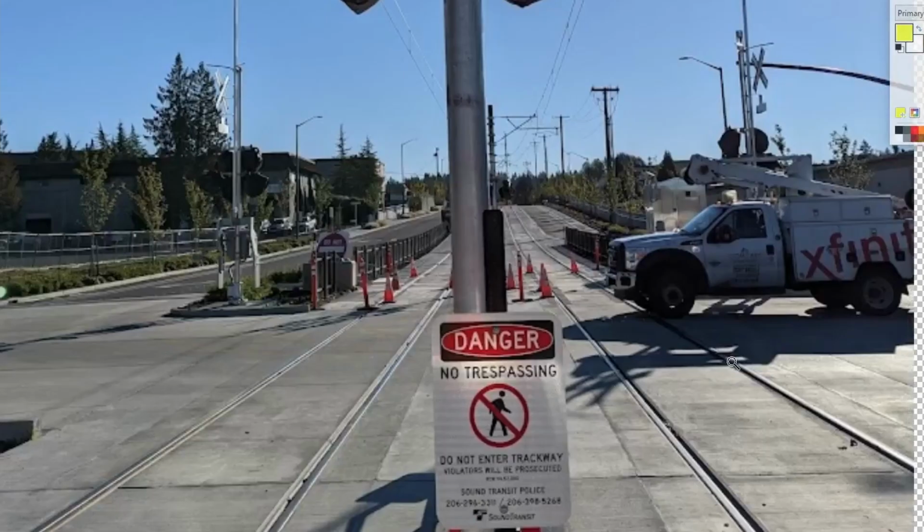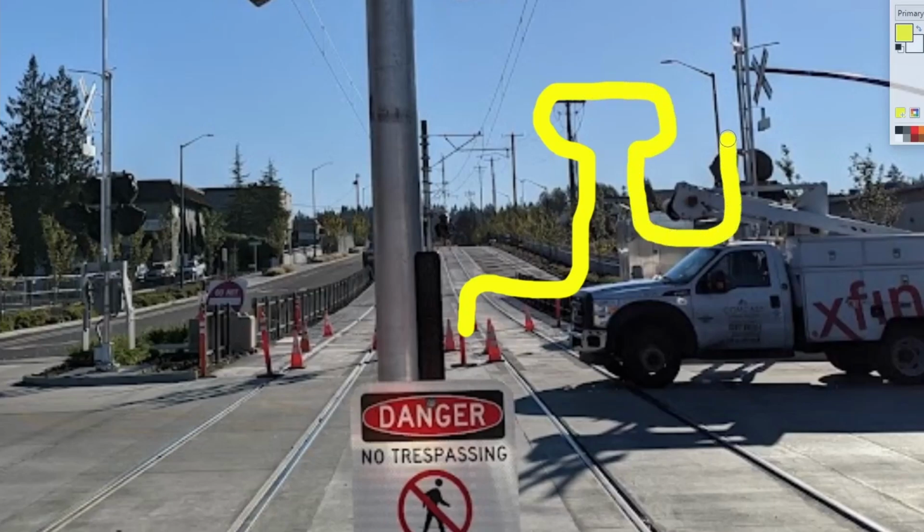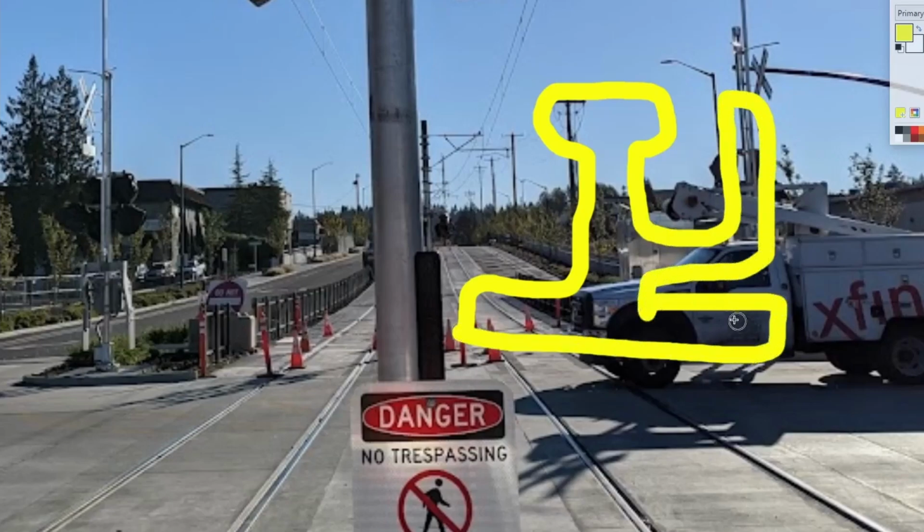So if you were to look at some embedded track like this, typically in your rail profile, you have your foot, you have your web, you have your head, and then assuming that the open spot of the gauge is to the right, you then have the flangeway built right in with an extra arm like that to hold off the rest of the concrete. Sometimes it looks like that, sometimes it's built into the foot, it just depends. So the flange of the wheel can still clear when it goes, but that way they can pour the concrete all the way off to one side or another. So this is a really unique rail profile that you'll see typically for trolleys, or again, a transit application, which is what this is.